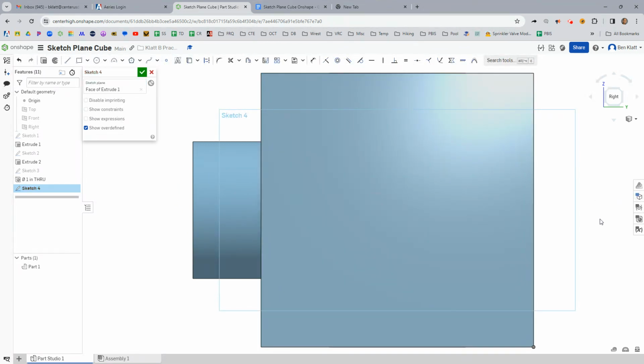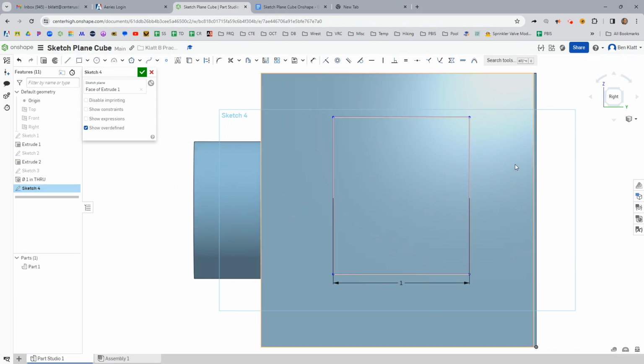So now we're already normal. I don't need to figure that out. Now there are center point rectangles, so we could do it that way. Let's just go ahead and do a corner to corner rectangle. Click somewhere, click. Now remember, that's going to bring up some numbers. I can put in a 1, Enter, which automatically takes me to the other one. I'm going to hit escape or just click somewhere. Whoops, I messed up. Again, escape gets you out of the command, or right click and hit escape rectangle.